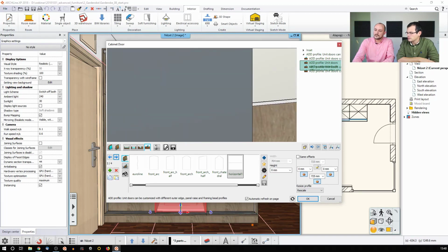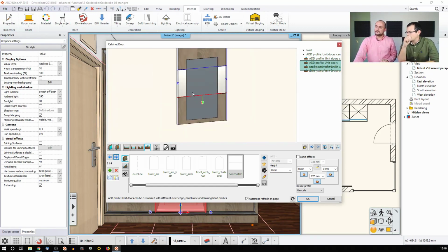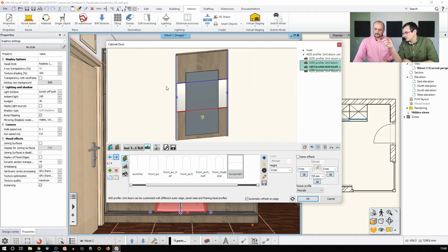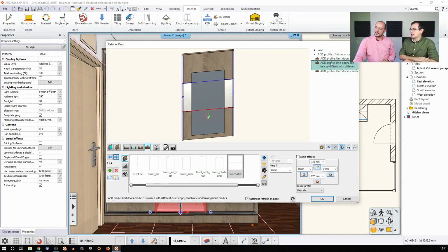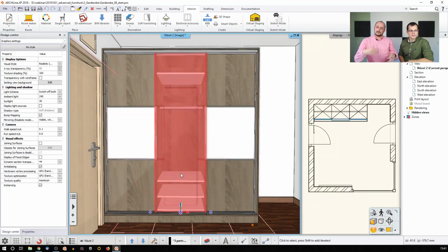And if you would like to see the cross section, how it goes, it looks like that, and there's a vertical bar, and that's swept along this path. One very good jump list is on the right hand side below insets. You can just toggle between the things. If your screen is too small and you don't want to see this, you can actually toggle this panel. But it's a good way to keep track of what you have added already. So this is how it was done, and then when you say okay, the software creates that.